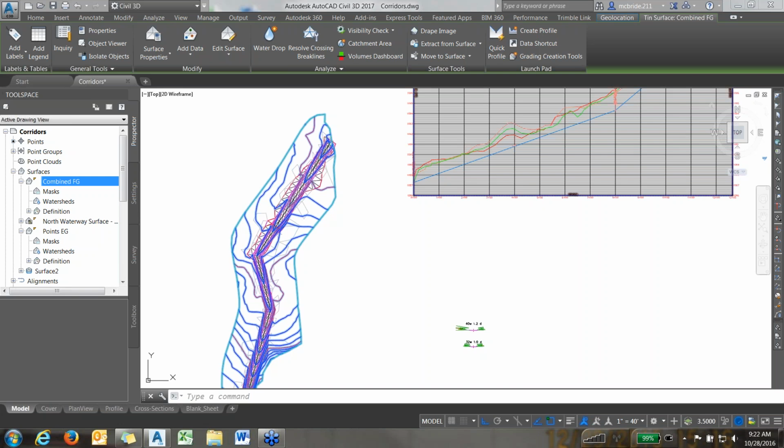Or if we were going more as a trapezoidal shaped ditch, or even a more complex shape like the two-stage ditch, or a shorter structure like a pond dam, the process could be done pretty much the exact same with just some few changes. You'd have to obviously rebuild the assembly with the sub-assemblies, maybe add a couple more components there. You may change some of your styles and how things look a little bit, but the process is the same.